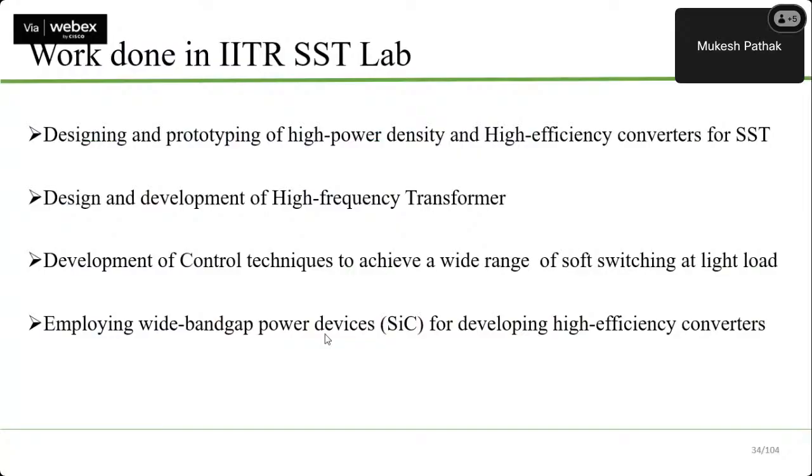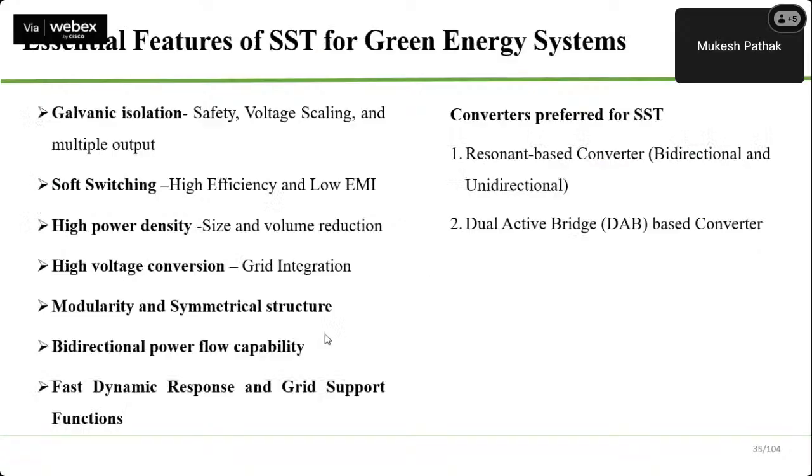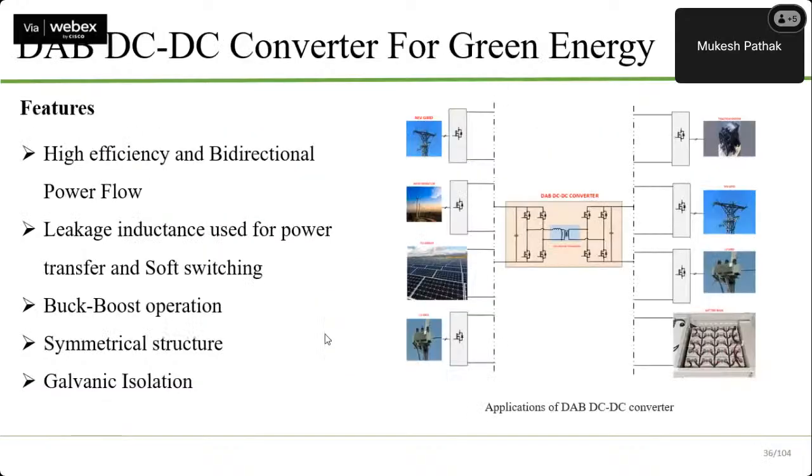And before I close, I'll discuss one or two solid state transformer systems that we have developed at IIT Roorkee. We are using SiC based devices and dual active bridge configuration. So this is a DAB based DC-DC converter for renewable energy integration.